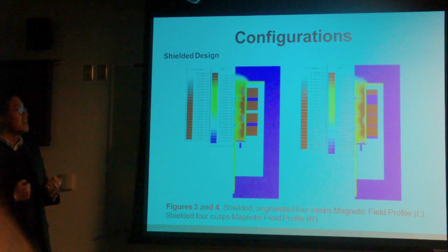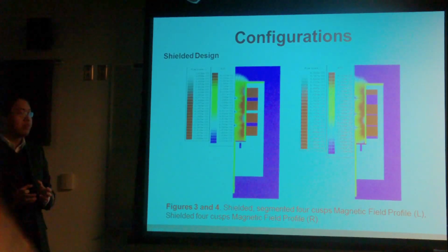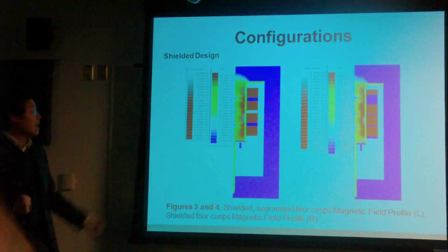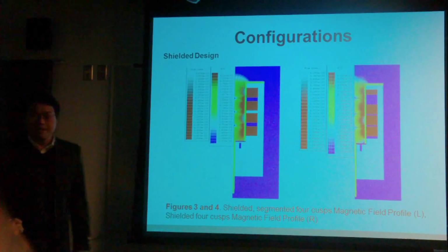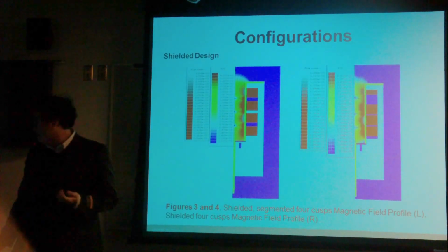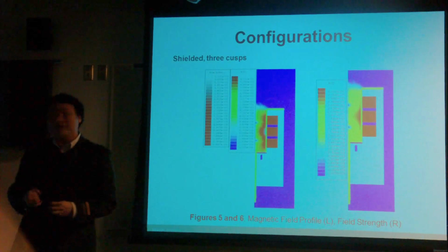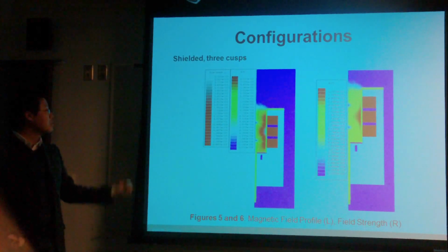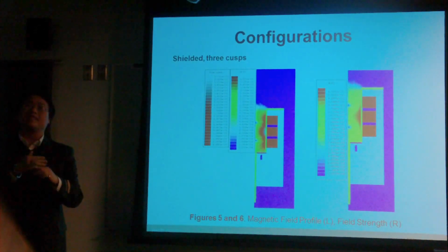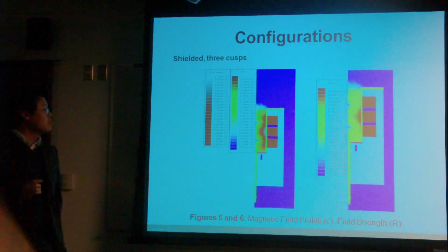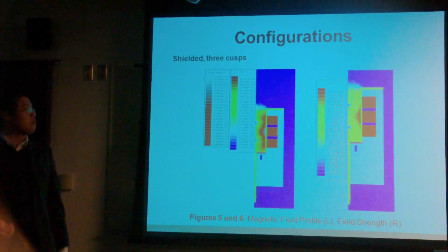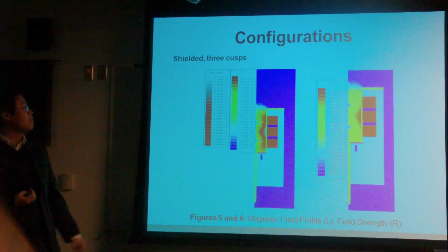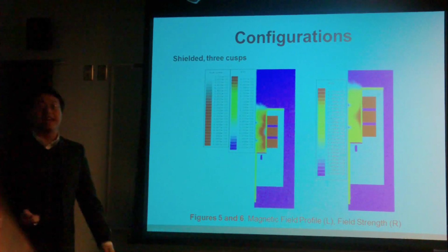The only problem is that it's not as desirable because the design is still bigger than the DCFT design because of the bigger magnets, and because the exit separatrix is so deep within the thruster. So we tried to address these two aspects in the further designs by using these shorter magnets I described earlier. So again, to get the thicker magnets, you have stacking magnets of the same orientation, which was very useful for making larger magnets with smaller magnets, but again, we still had the problem of not having optimal topography. We had weak field strengths, as you can see in this diagram, at the anode, which was not desirable.